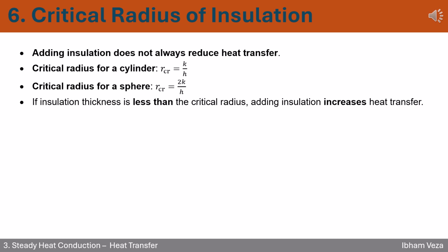6. Don't be fooled by insulation. More insulation isn't always better. In some cases, adding insulation actually increases heat transfer, especially in cylinders and spheres. This is where critical radius comes in.